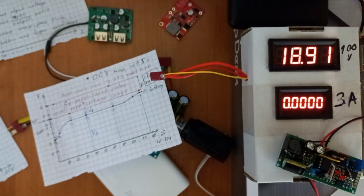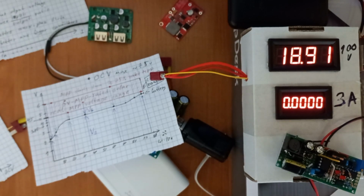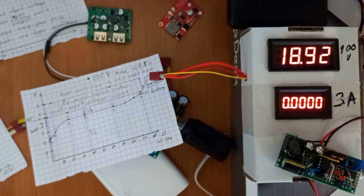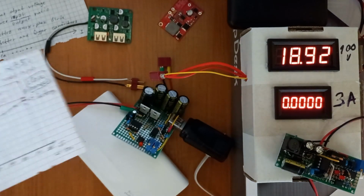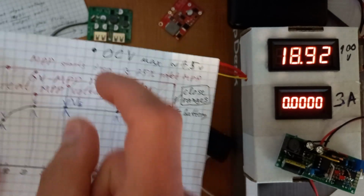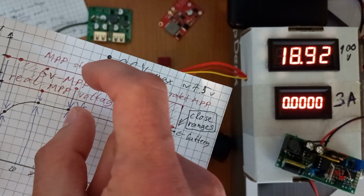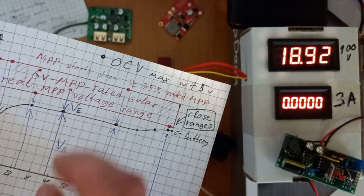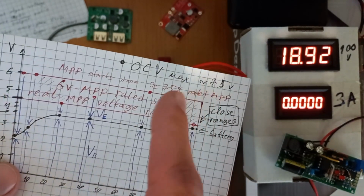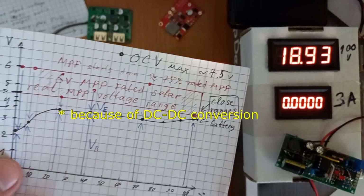Realistically, with correctly designed system, you can expect an MPPT device benefit of around 20 to 25% comparing to direct connection. The more distant the battery voltage from MPP voltage, the more benefit from MPPT, as you can see from this chart. So you convert this excessive voltage to extra current. But for overall best efficiency, it should be close. These ranges should be close.